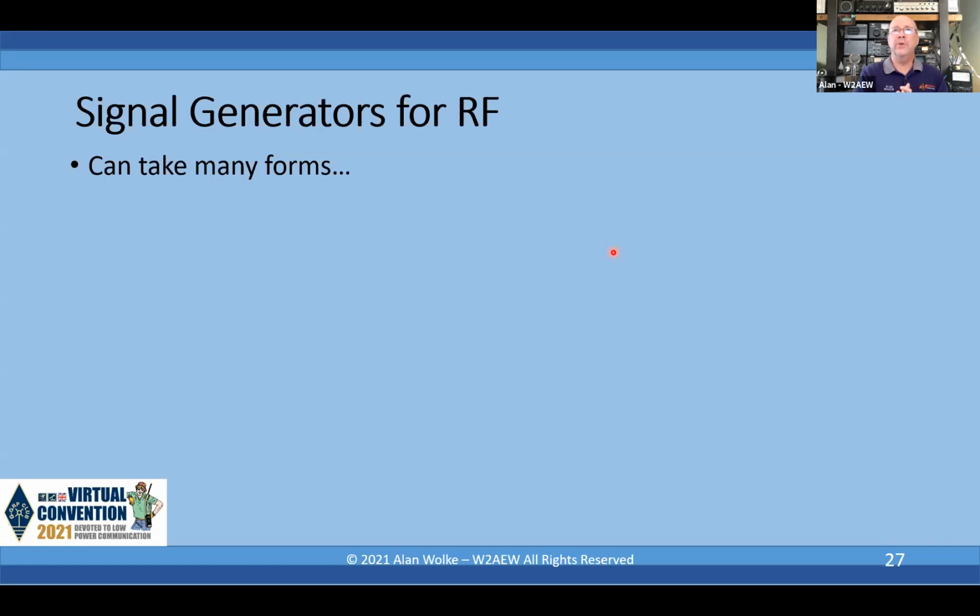So, okay, Ron asks, in general, which is more useful to us radio amateurs, the VNA or the SpecAn? I would say, if you're a builder and experimenter, then probably the VNA, because if you often need to compute impedance matching networks and things like that, then the VNA is more useful. If you're primarily looking at the spectral purity of an oscillator or harmonic content of a PA that you designed, then the spectrum analyzer is needed. But it really comes down to the type of work that you're doing. Almost either one of them could be more important depending on what you're doing.